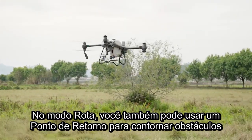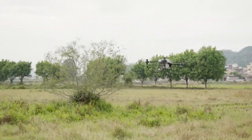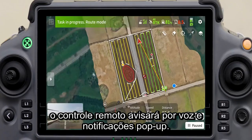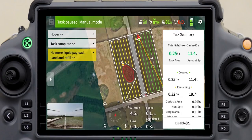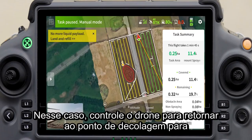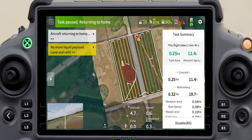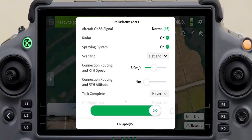In route mode, you can also use a return point to bypass the obstacles encountered. When the liquid pesticide is used up or the battery is low, the remote controller will prompt with voice and pop-up notifications. In this case, control the drone to return to the takeoff point for refill or battery change. Then, click Resume to proceed with the task.